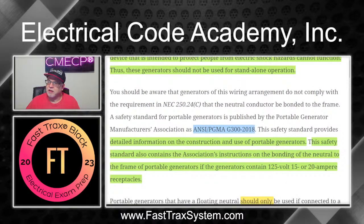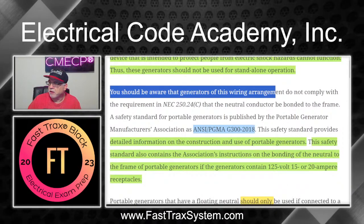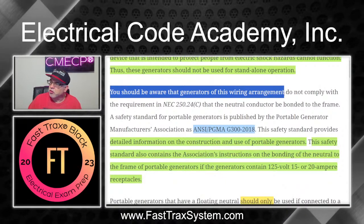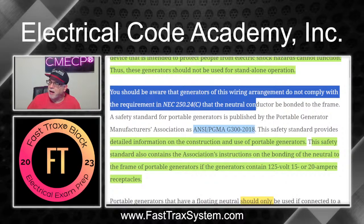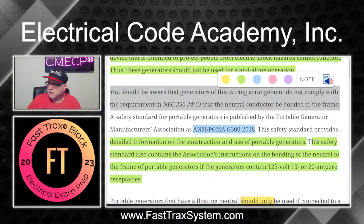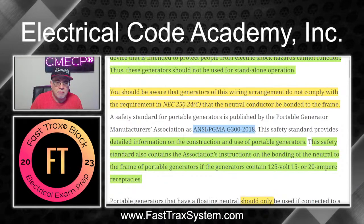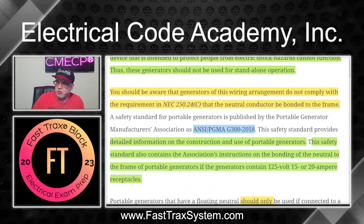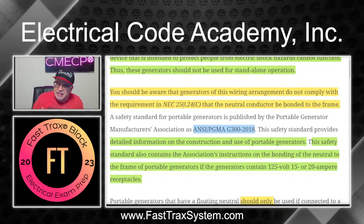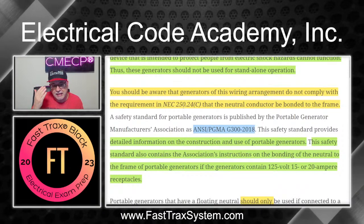Let's read a little more here. It says you should be aware that generators of this wiring arrangement, that is the one that's the floating neutral, by the way, do not comply with the requirements of 250.24(C) that the neutral conductor be bonded to the frame. Okay? So again, first of all, trying to meet NEC rules, and this is going to become even more important if you happen to try to use one of these generators to supply like a dwelling or something like that, then it becomes pretty critical that it can't comply with 250.24(C) if it's a floating neutral because you don't have that neutral to the frame connection. Okay, that's a problem, right?